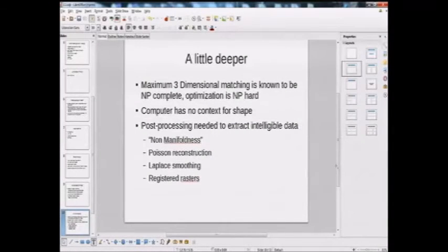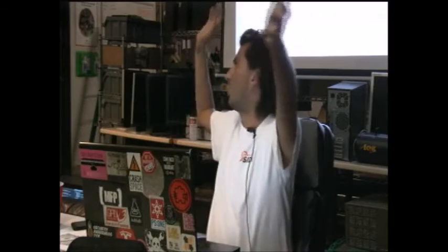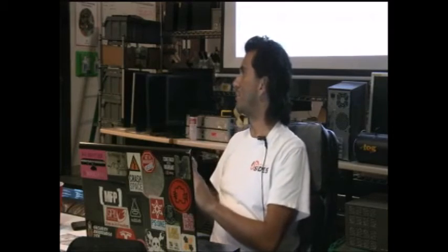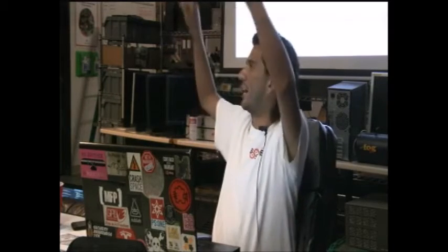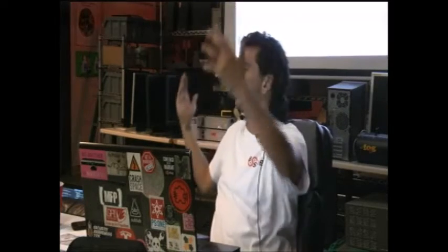A couple other things we're going to have to consider that aren't necessarily clear right off the bat: when we're processing the point cloud, turning it into the STL where we have the triangular faces drawn between every little point. It's easy for the computer to visualize just a big messy point cloud with a million points in space, but once you try to stitch all of those points together, sometimes there are little dangly points or edges just floating out in space.